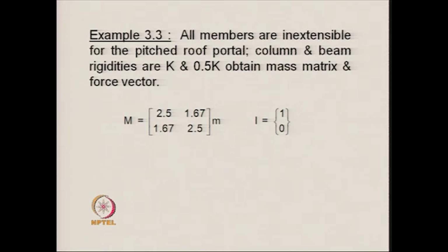The second form of equation was in terms of the total displacement of the structure, in which the second order differential equation had the total motion as the unknown. On the right hand side, we had the stiffness multiplied by the ground displacement plus the damping coefficient multiplied by the ground velocity.